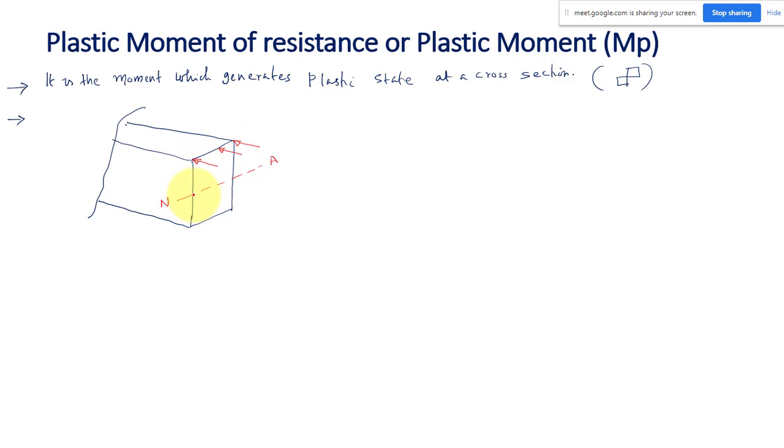So what is the stress at this neutral axis? That will be 0. In between, what is the variation? There will be linear variation. Let me draw it in 3D view, so it will be much more clear. I think you are getting what I am trying to say. This is the compressive stress acting. Again, it's a bending stress acting normal to the cross section. What will be this angle? This angle will be just 90 degree because it is a normal stress acting perpendicular to the cross section. This is the stress acting above the neutral axis.